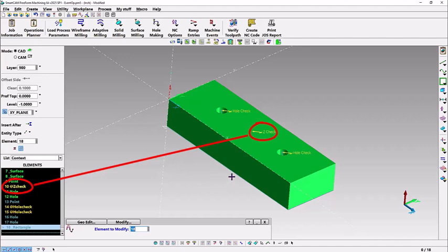I've used it here for doing a machine stop, and then to check the Z level, and then it'll spot drill the 2 holes, and then it'll let you check the hole positions, so you can check the Z and then the X and the Y's on this.